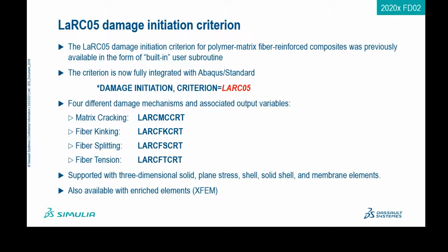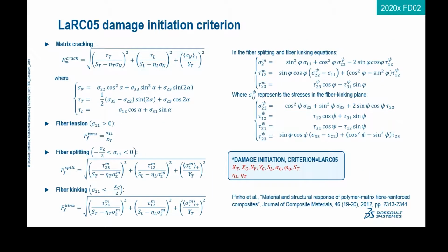It's supported with three-dimensional solid, plane stress, shell, solid shell, and membrane elements. And it's also available with enriched elements using the extended finite element approach.